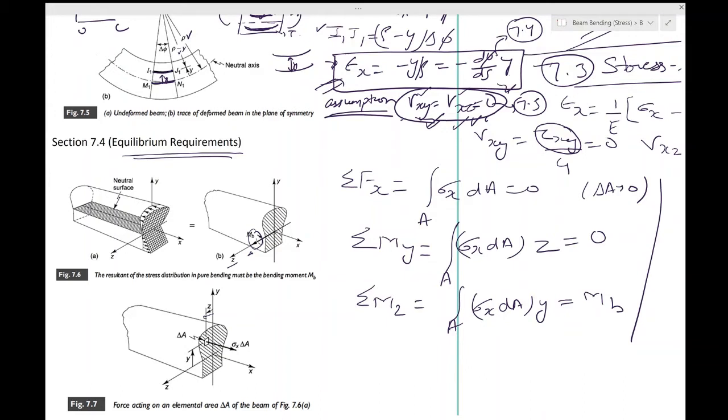Now here we again make the fundamental assumption that the deformation of the cross section is sufficiently small so that we can use the undeformed coordinates to locate the points on the deformed cross section. So when we chose this element y, we chose this element z, it was in the undeformed situation, but we continue using the y and z even in the deformed configuration, because that point of concern, the center of this area, has deformed only slightly.